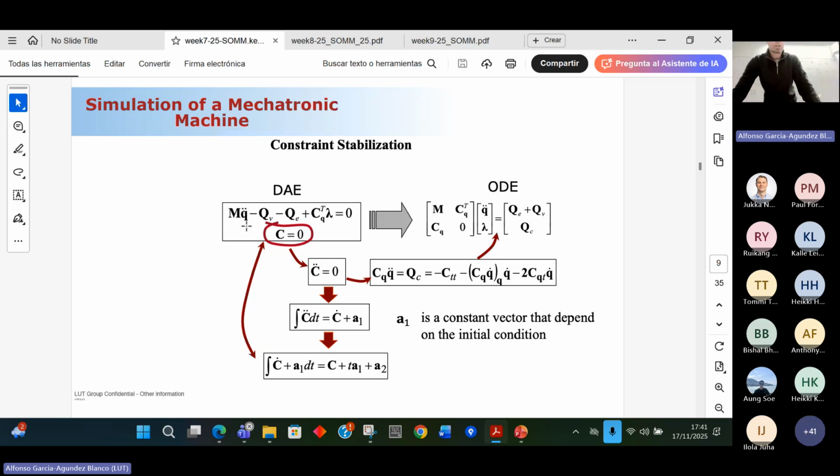In the dynamic equations, you have this first term, the mass matrix M times the second time derivative of q, which represented what? What was the meaning of M times q double dot? That term represents the inertia forces, okay? Why inertia? Because you see here the second time derivative of the coordinates, which is acceleration, okay?